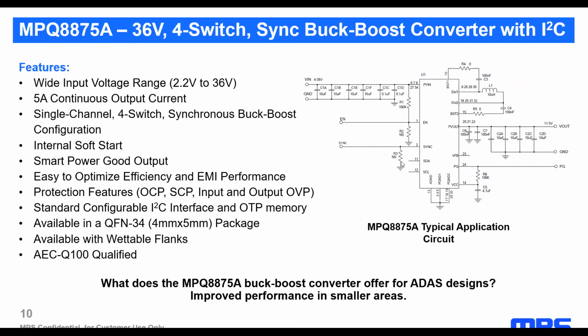For example, there are some chips where the soft start is configured by an external capacitor, while in this case, the soft start is configured by the I2C interface. We avoid using an extra capacitor and making any rework during the design.